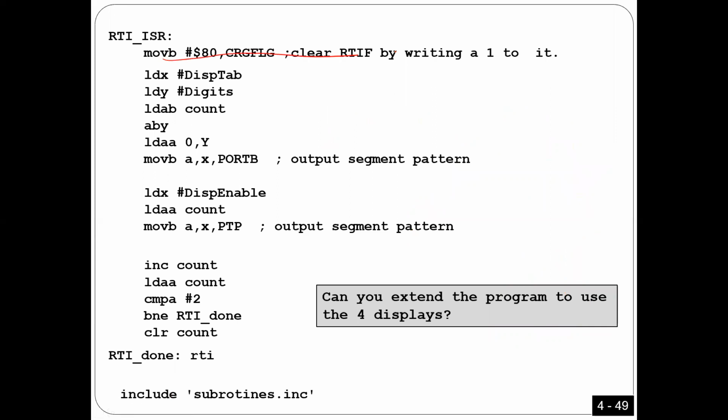First of all, you have to for sure write this instruction to clear the flag bit. We always do that. Second, now X is pointing at the first location in display, right? This is this array. This array has the 7 segment code, and the second one, register Y, should point at the beginning of digits, right? So remember, this one has numbers from 0 to 9, all the codes, right? So anyway, let's see how it works, guys.